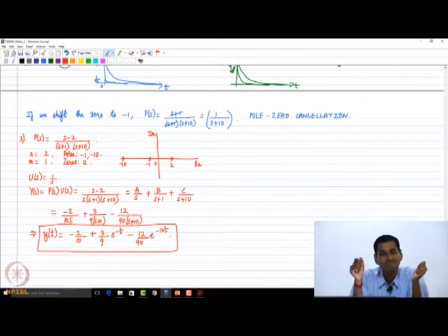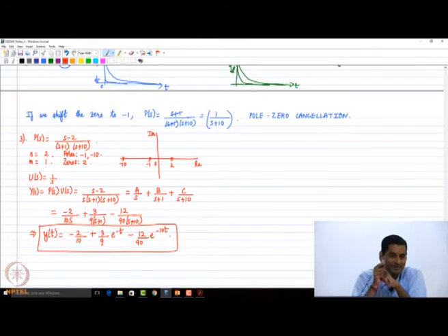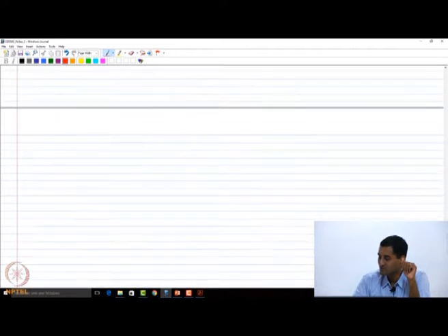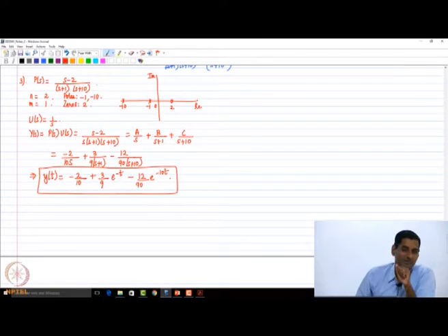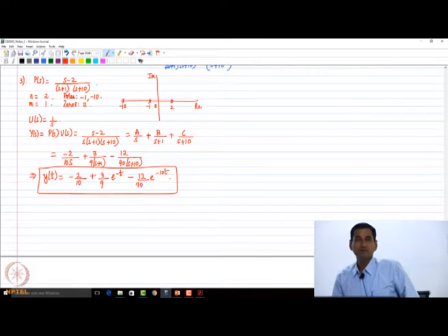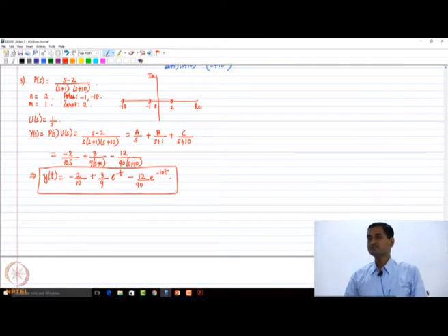So regardless of the pole being dominant, the 0 will decrease the residue, but from a pragmatic viewpoint, we are interested in what is happening in the vicinity of the j omega axis, right? Because the poles located in the vicinity of the j omega axis would dominate the dynamics. Okay, so that's why they are called dominant poles. Okay, so can you observe something else?